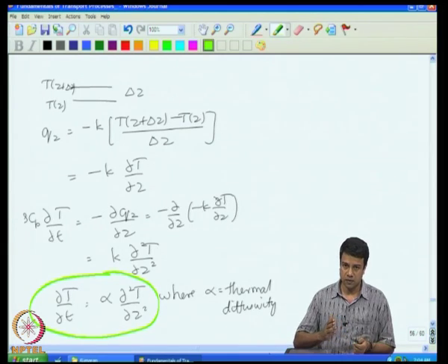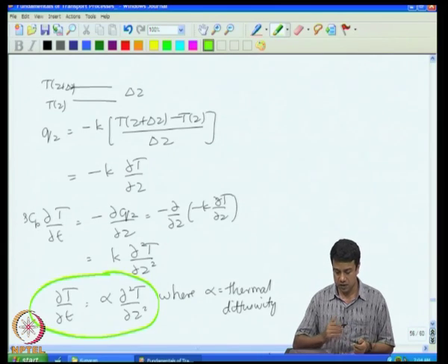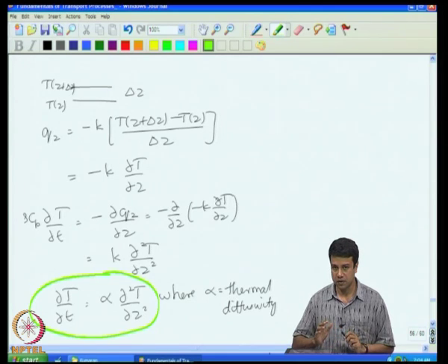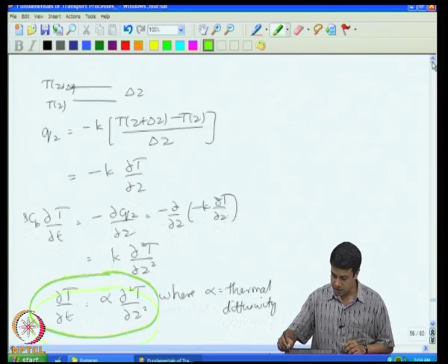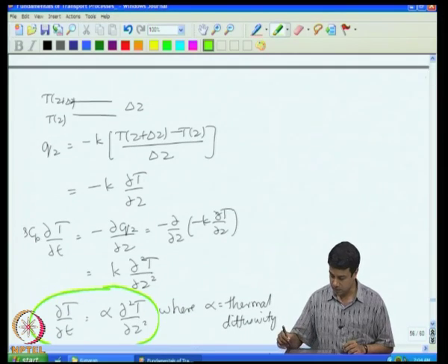We have first considered the simplest case where it is at steady state. So, there is no variation in time. Then d squared T by dz squared is equal to 0, temperature is just a linear function of Z, easy to solve. I introduced the concept of scaling just so that you can be aware of it at this point. Next class we look at other unsteady problems.